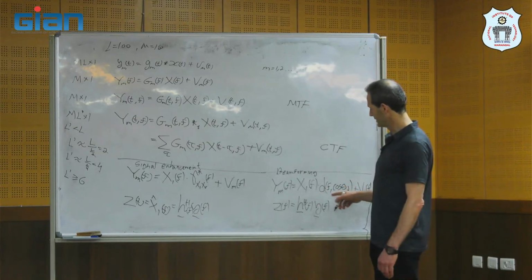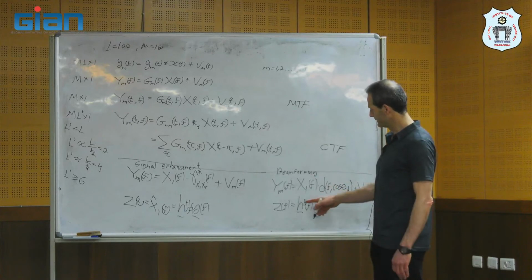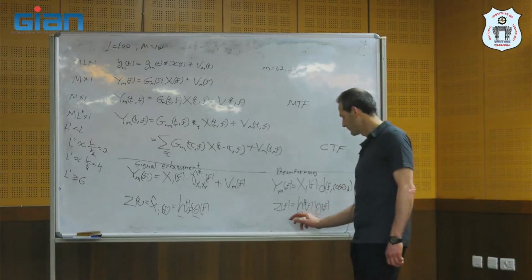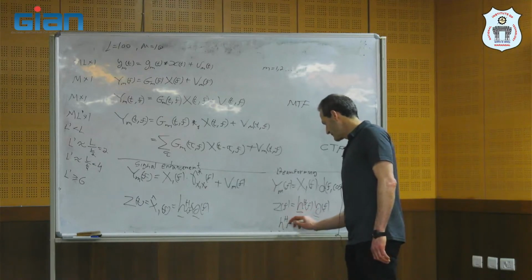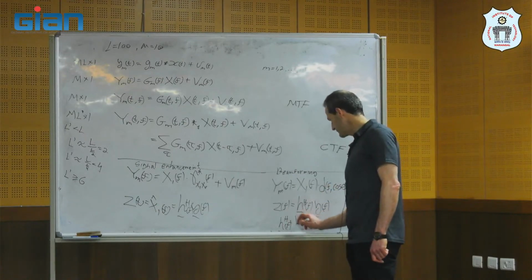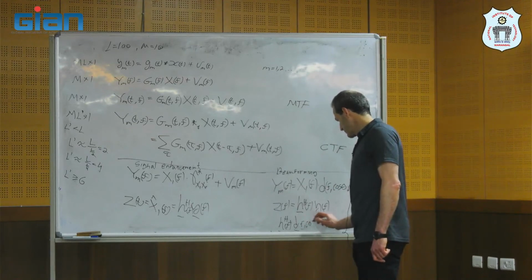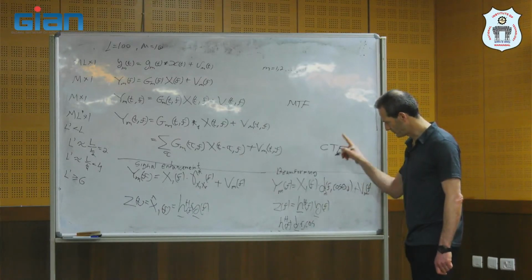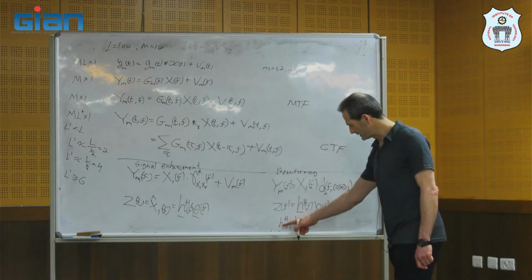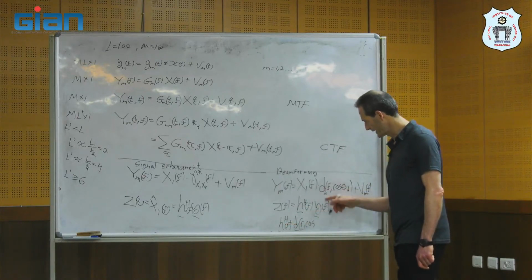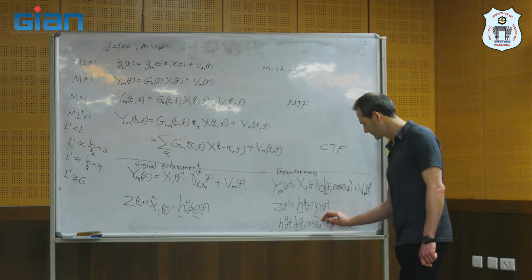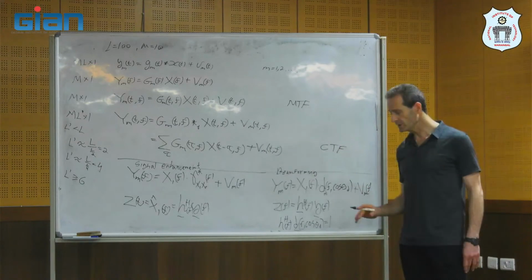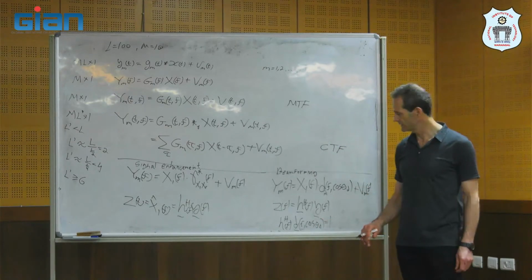So here we need to apply a requirement that if h, the beamformer, is applied to the steering vector d_m, by the way, here you need to add m, so this is the m-th element of the steering vector, which contains all the m components, theta d, it is required that it will be 1, so we have a distortionless response of the array towards a certain direction, theta d.